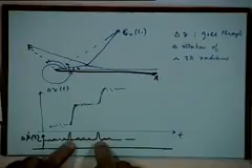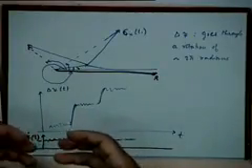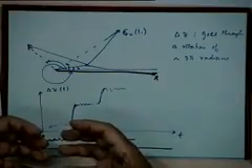So how does that picture change when your behavior of noise is like this? The picture changes in the following way. Although that picture is still valid, but the fact is that these sudden jumps in the output, or these pulses in the case of FM, they have significant amount of low frequency energy.